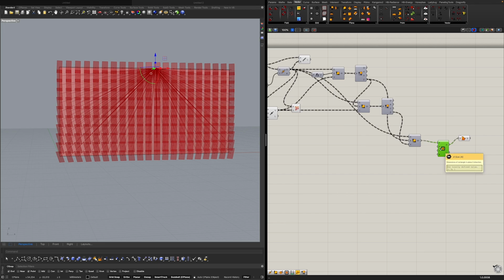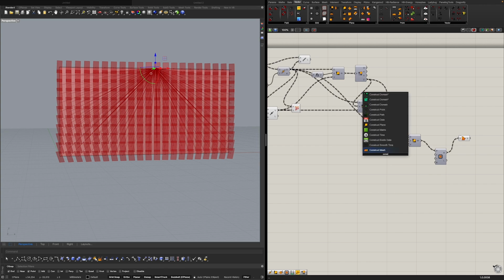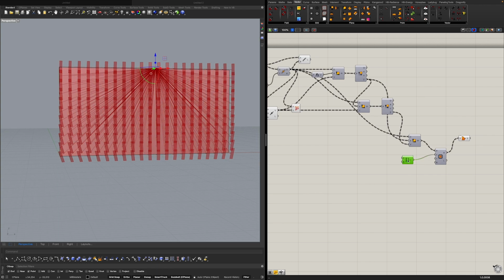You can use X and Y size here as inputs, and further you can see that they will take a domain value, I mean, from negative value to positive value. See, one locally defined value, -1 to 1. So further, what I could do is create a domain, construct domain. What domain does is that it takes two values as input, like you can give one input with two values. So I'm going to just plug this in X, copy paste, and Y as well.